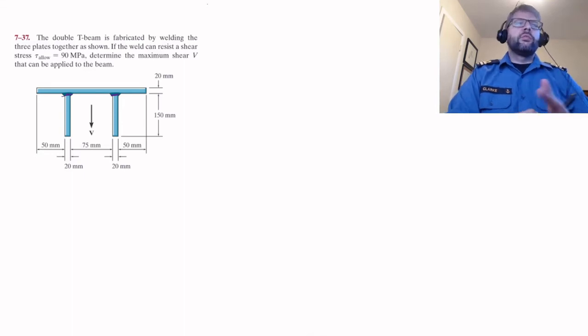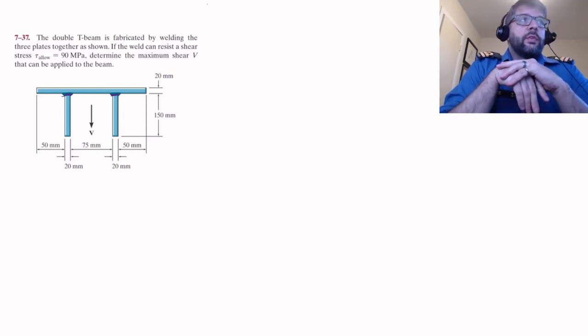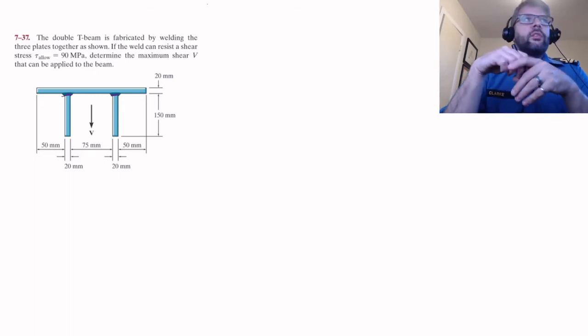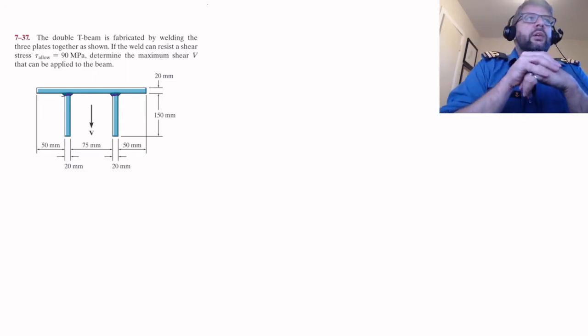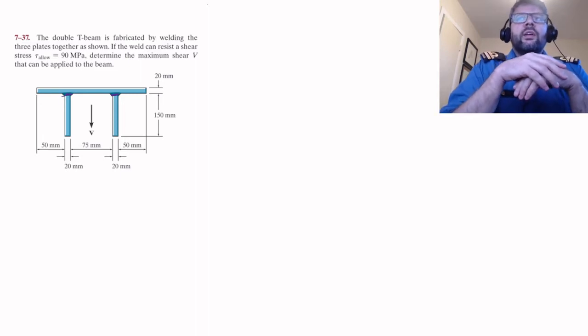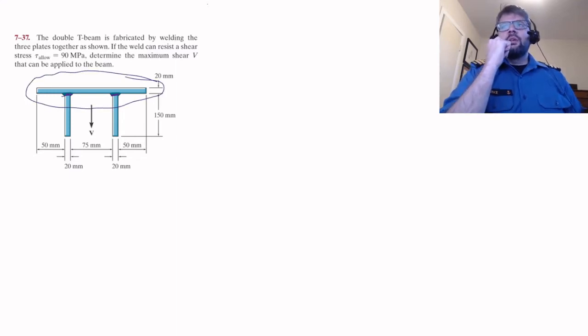So this is one of the key instances where you're really going to be worried about the shear stress that's arising, and not necessarily the bending stress, because this is where your shear is causing the tendency for these things to try to slip relative to one another, whereas here the bending moments, obviously the bulk of that would be held by just that top bar there, and then some of that down here as well.